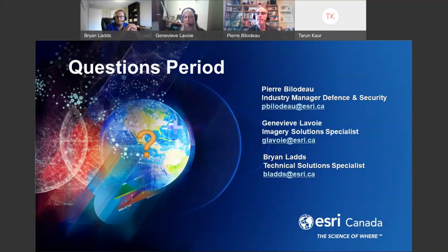Because sometimes if you don't have the GCPs, you see that your product is underground or above ground, and then you add your GCPs and it will make the correction. But if you do want to do it manually, yes, there is an option that you can do that. It would be in your coordinate system. You can put a geoid height.